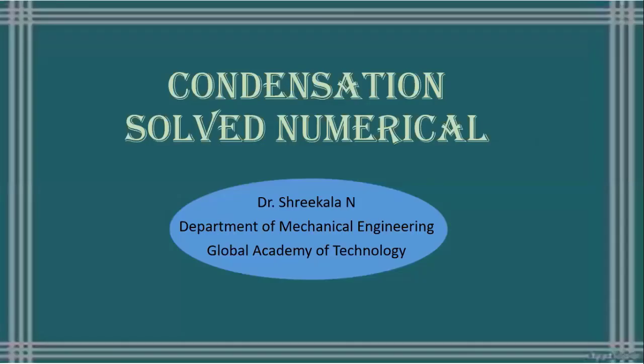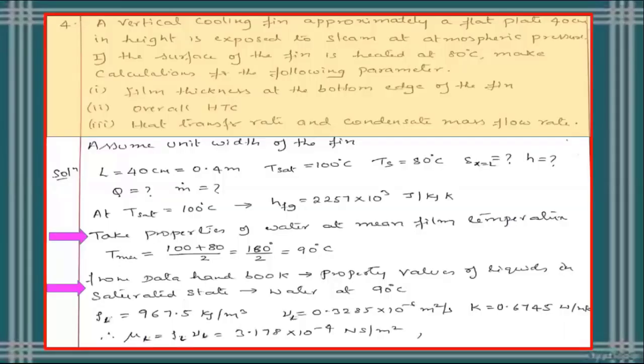Hello, my dear students. Today, in this lecture, let us solve some numericals on condensation. In this problem, it says a vertical cooling film, approximately a flat plate 40 centimeter in height. So the height of the plate is 40 centimeter, that is nothing but the length L as 0.4 meter.